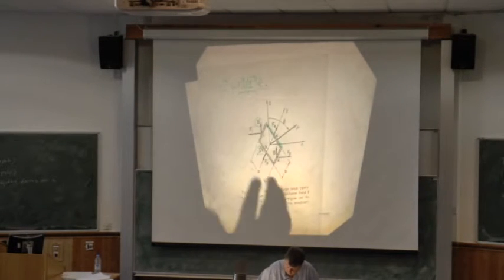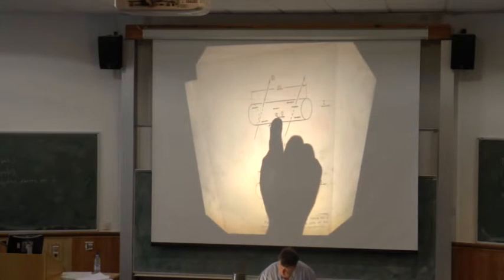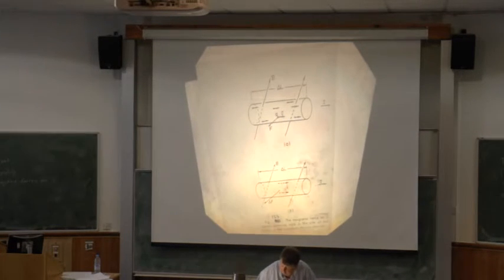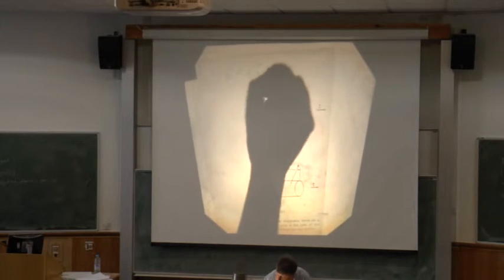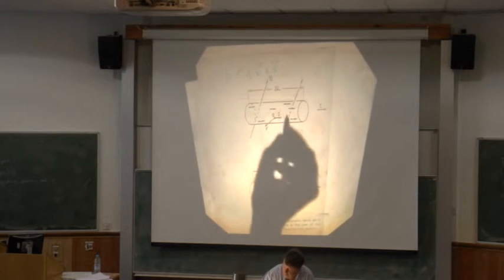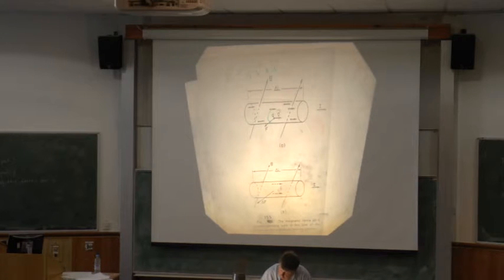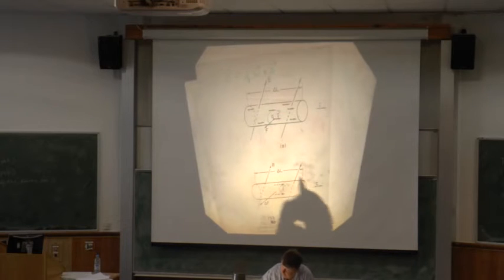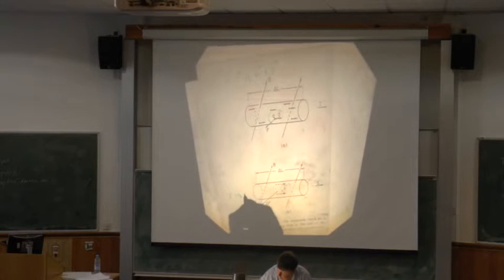This force law itself, of course, we've done this several times. It just follows from the Lorentz force. If you analyse all of the charge carriers moving with some velocity v inside a wire, each one of them experiences the force F is Q v cross B, and then you turn this, using the kind of arguments we've used many times, into a picture of current density, and then we integrate over the area of the wire, we get F is BIL.